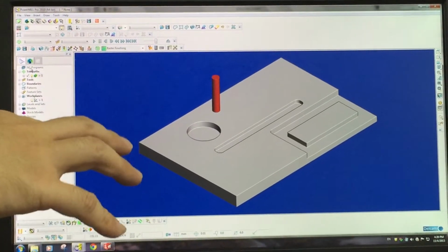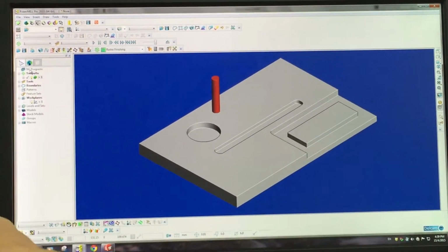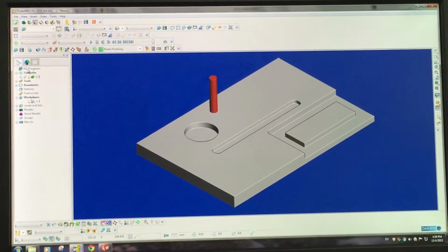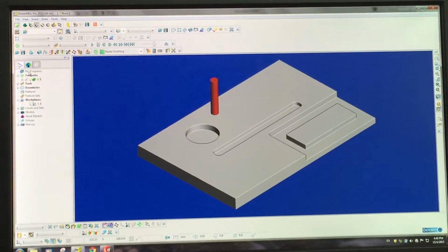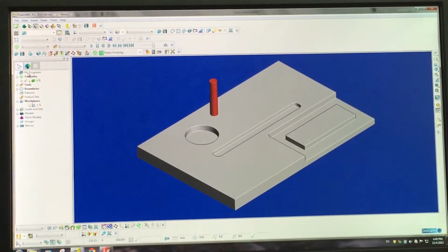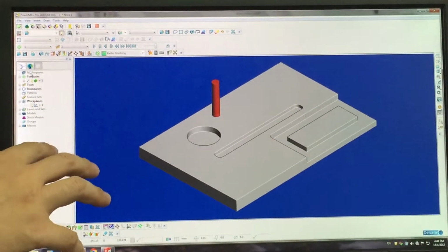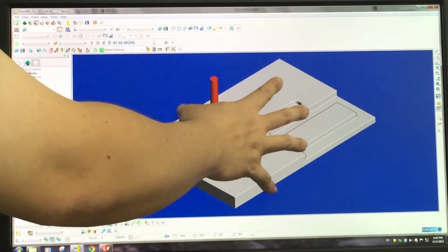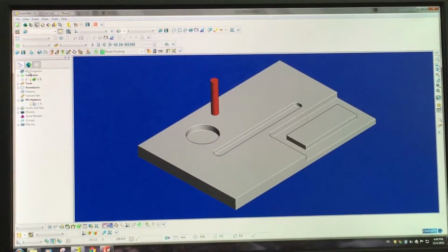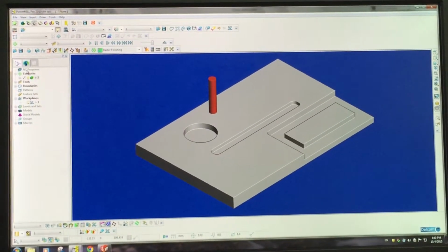But when you come for your CNC practical, make sure you bring your IGS file. Up to the simulation stage, you can do it also in the computer lab just to practice. What you cannot do in the computer lab is transfer this toolpath to the NC code. There's one step before you transfer.